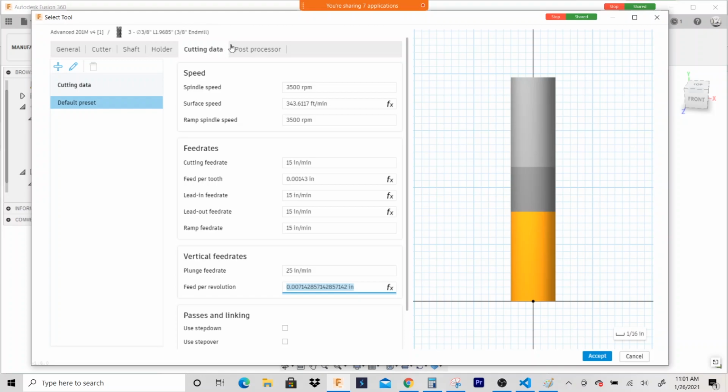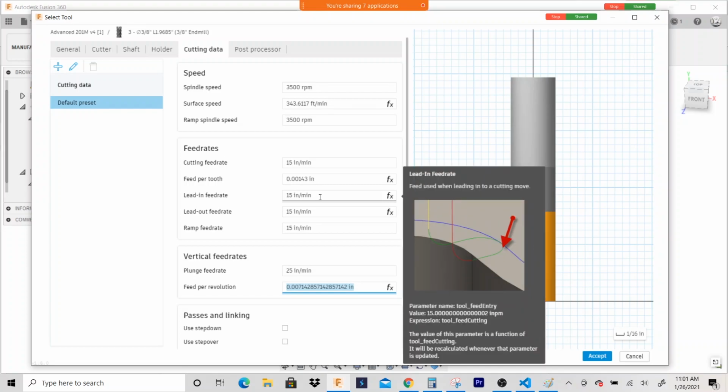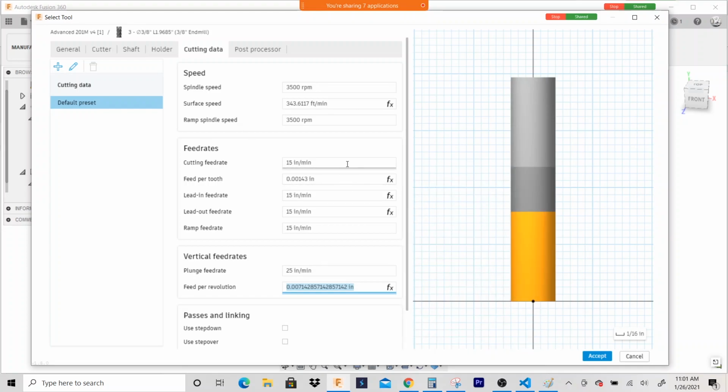I like to start off slow on the feed rate, and then at the machine, when you go to run it, I usually start off at about 15 inches per minute. Then on the machine, I'll override the feed rate, keep going faster and faster, and see how far I can push it. You basically have to watch how the shavings come off the part. You want nice C shapes, and you want to listen to it. If it starts rattling a lot, you may want to slow down the feed rate. But once you get a feed rate that's working well and it's not breaking tools or burning up end mills, then you go back to the CAM software and enter that feed rate.